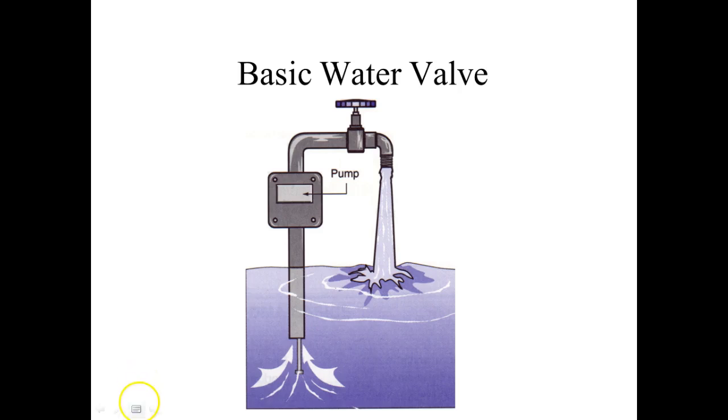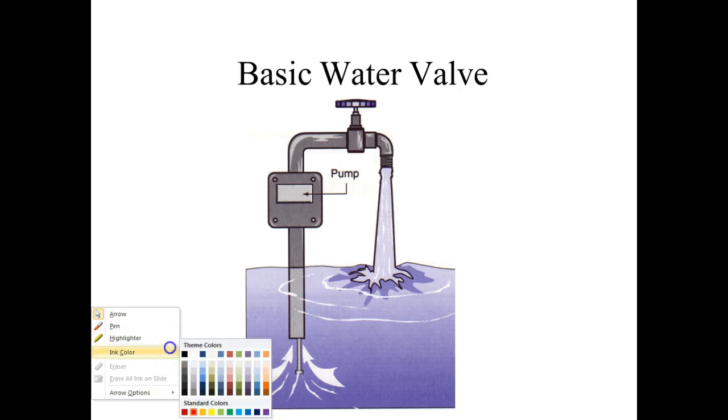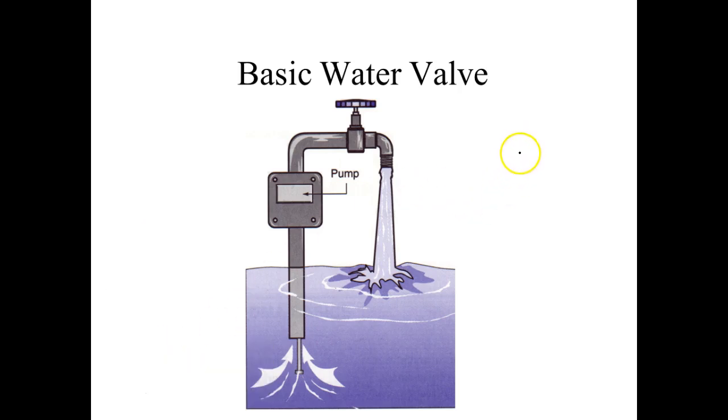So what a transistor is, all transistors are current valves. The only change is how we change the size of the valve. So the actual valve, this is the symbol we've already looked at a little bit. We call this the what? The one with the arrow on it, we call that the emitter. The one without the arrow, we call that the collector. And that's our valve right there, guys. That's the valve. It's the current flow between the emitter and the collector. And instead of controlling the flow with a knob, we control that flow with this guy right here.